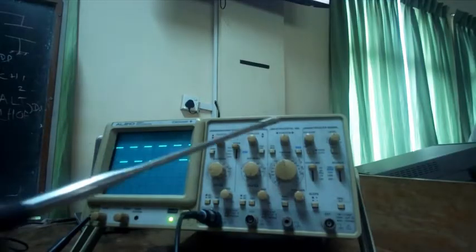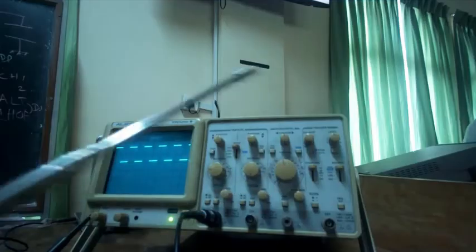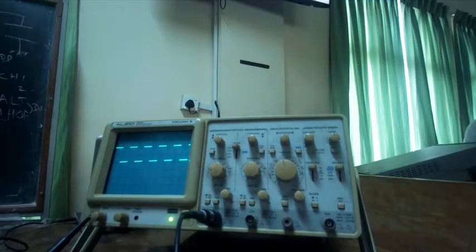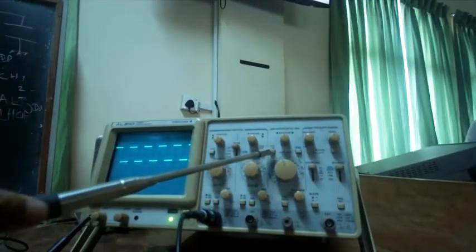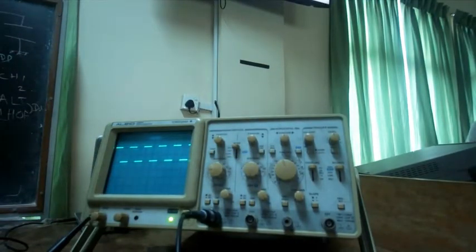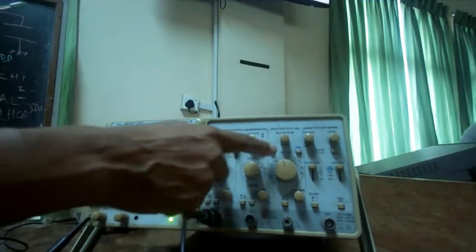It's not hard. And also you know this time per division, the sweep controller, and some also have a magnification button, which means if the sweep rate is 10, you are amplifying it faster, right? So the slope is 1 division per second. It will be 1/10 of a division per second. So it's faster, right? Slope is 10 times higher. Magnification by 10 is that.